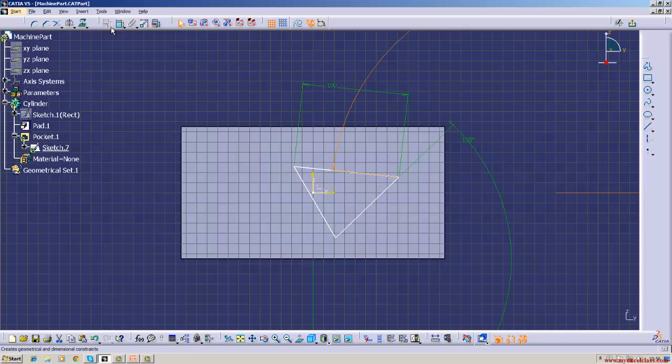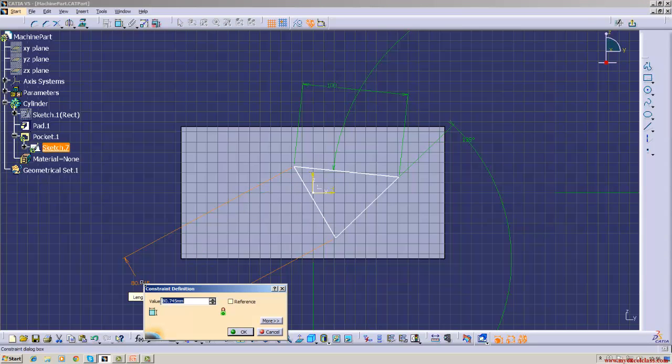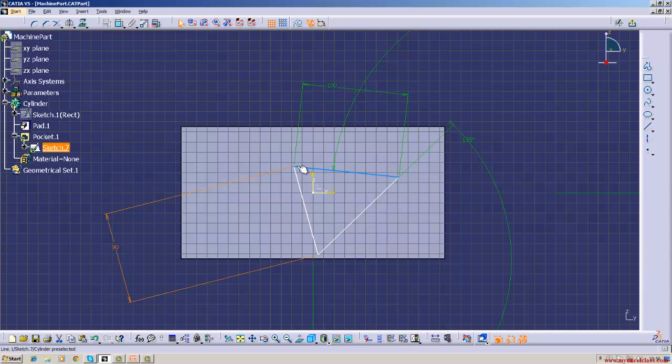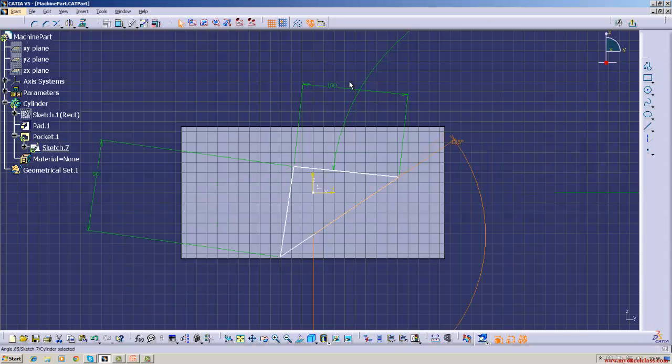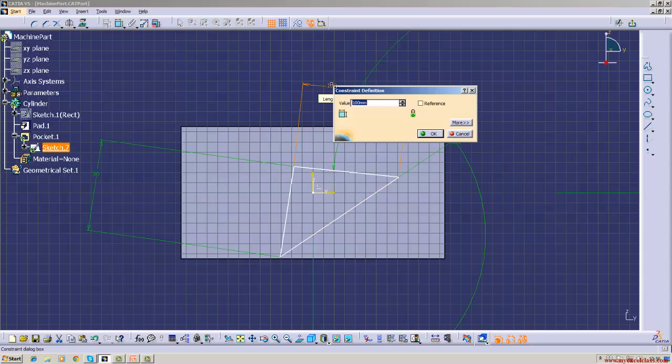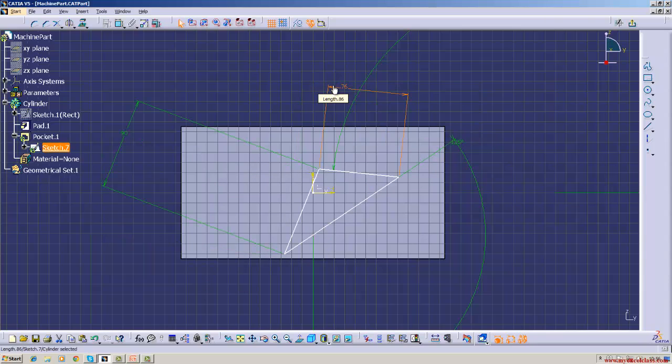And this I can change. Suppose we change, what is going to happen is the connectivity between these 2 points is maintained because this is a balanced constraint. Similarly, we can change anything here. See, 125 we make it. The figure, you can change 75, 76. Like this you can change. This is constrained. Suppose you add one more dimension, it is going to be over constrained.